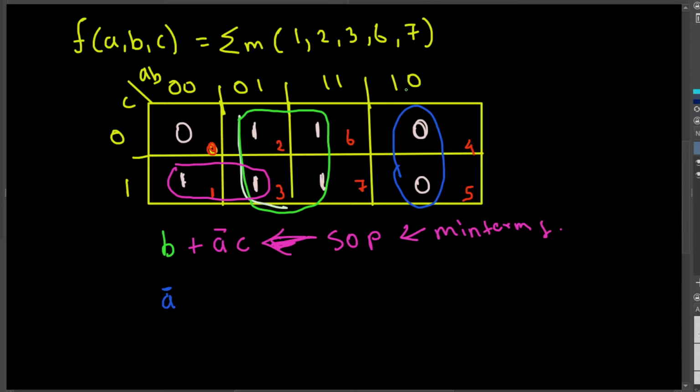When we have A, B, if I group them together, that's an AND gate. But when we do the product of sum, there's an OR gate. So I had to put a plus sign, and then B is 0, so it's going to remain the same, and then a bracket. And after that, can I group anything as 2? The answer is yes, because when you draw a K-map, you have to think, when you fold it, can you connect 2 of these? So you just look at the ends, and at one end we have a 0 right here, and in the other end we have another 0, so we can connect these two together.